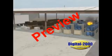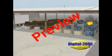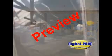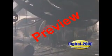At the EQ facility in Apex, the bays were separated by 6-inch-high curbs, designed only to contain spills. The CSB determined that firewalls would likely have contained the initial fire in the oxidizer bay, preventing it from spreading to other bays where flammables were kept. The only fire control equipment at EQ consisted of portable fire extinguishers, which were of no use when the open bay facility was unattended.